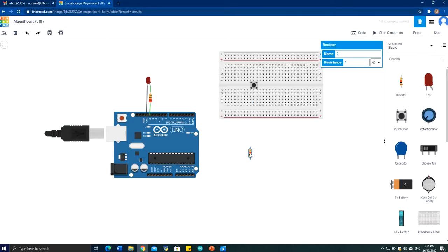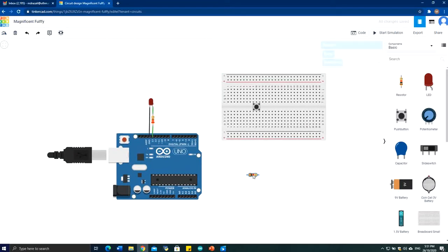For this particular case, let's rotate this component first, and then put the component in the breadboard. Okay. For the push button, when you press the button, this will be connected. Once you release it, this will be unconnected. So what you can do is, for one part of this push button, we can connect this part straight away to the ground. So this is the ground connection.